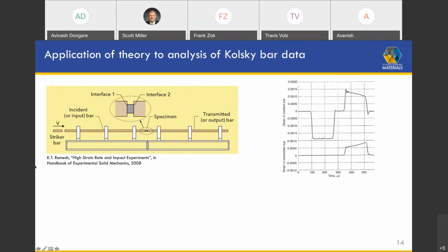So you can, for example, put in a thin shim of a metal at this interface here. And that will slow the ramp up to the peak pressure, but it reduces the overshoot and the subsequent oscillations in the stresses due to the dispersions.